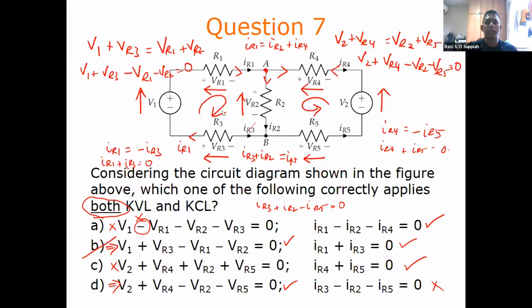The arrow that I draw here indicates the voltage: the head of the arrow is higher voltage, the tail of the arrow is lower voltage. The arrow that is drawn on the line itself, the branch, is the one indicating current flow. The arrow that I'm drawing here is actually the plus and minus; the plus is higher voltage, minus is lower voltage. So it's two different things. One is voltage, one is current.